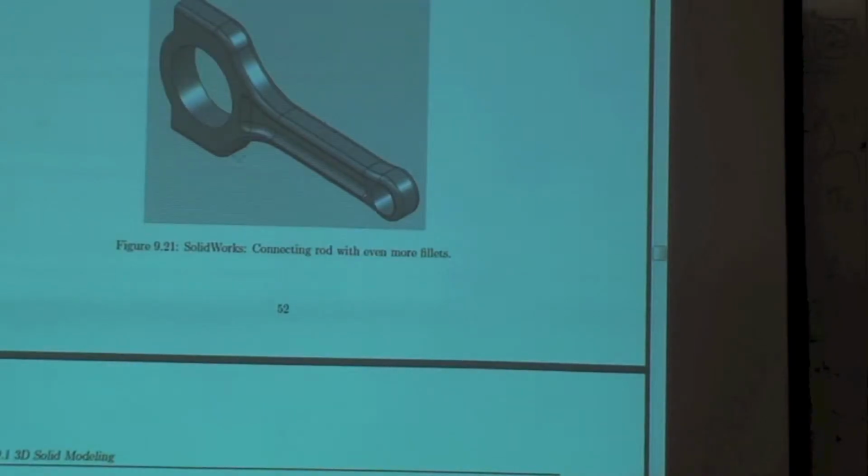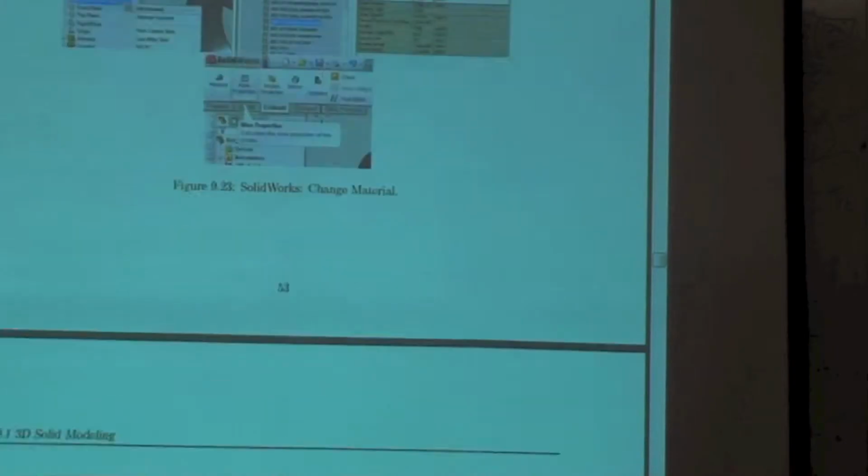I didn't fillet extensively because when you go to Abaqus, the problem is if you fillet a lot, then you have to have very small mesh. It's a student version of Abaqus, so you're only limited to a small amount of element size. So you've got to be careful with that. But you can still get a pretty good model of it.